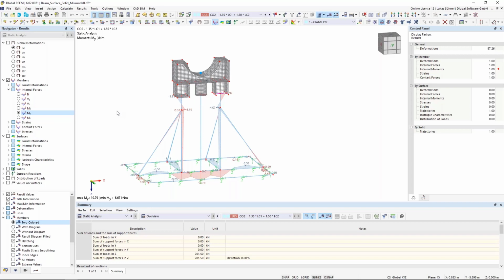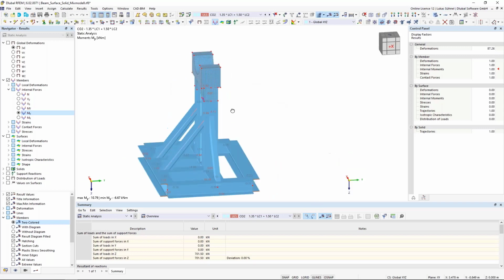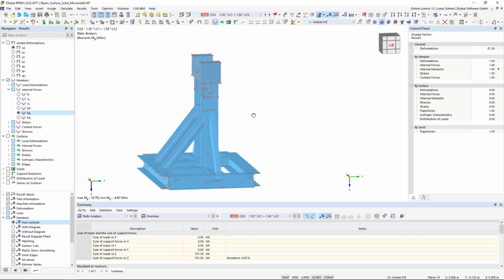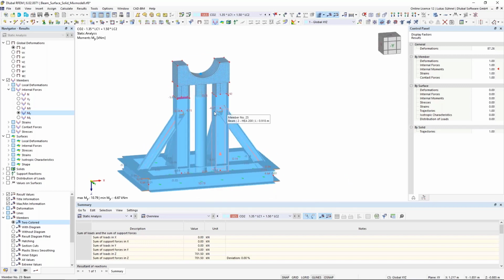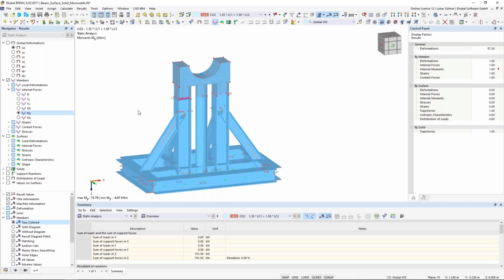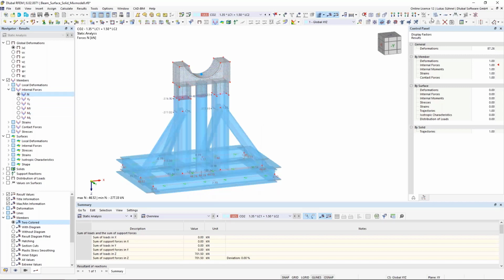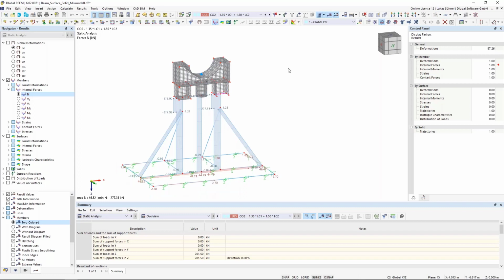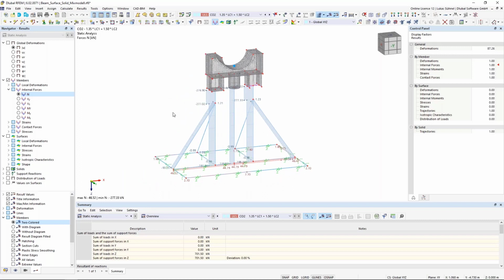What does it mean? If I neglect the bending moments, then lateral torsional buckling is most likely not an issue. And if I check again my structure, I have all these diagonals here that are connecting to my columns. A pipe section, which is where lateral torsional buckling is not important at all. So I think it's fair to say lateral torsional buckling is not an issue here. What could be an issue is, of course, buckling. But for buckling, I can use some limit checks or, let's say, some specific checks to judge if buckling is actually an issue. And such a check can be found inside the Eurocode 3 in chapter 6.3.1.2 in brackets 4.